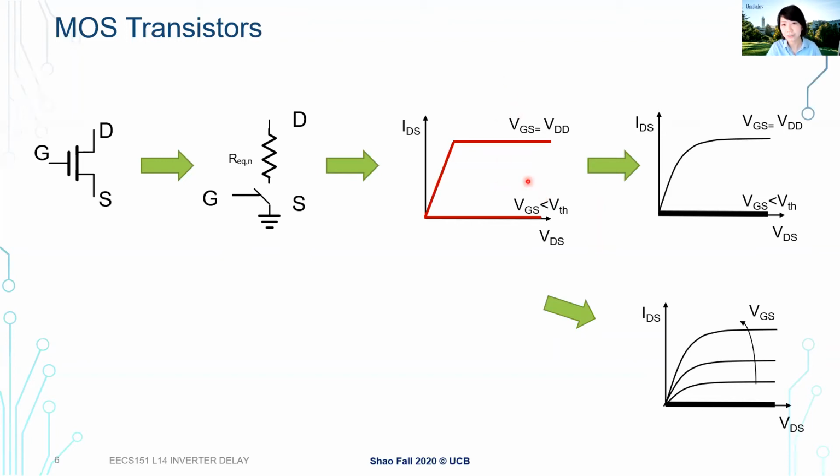Good question. What Prashant asked earlier is basically the saturation region. Again, three regions: completely off, less than threshold; linear region, just like a resistor, nothing fancy; and then saturation, because we cannot maintain the threshold. Those are the three basic modes of our CMOS transistor.